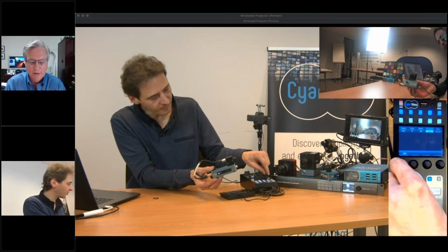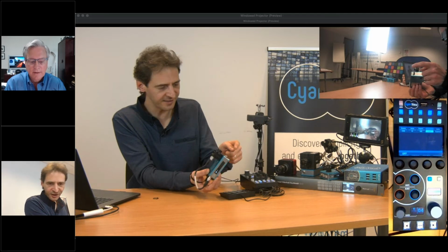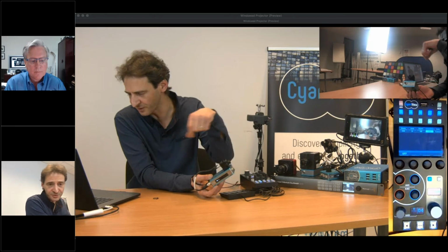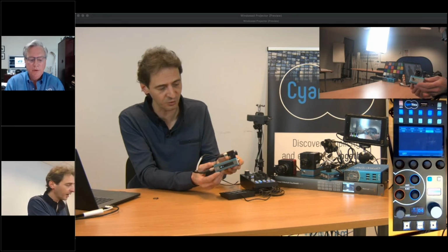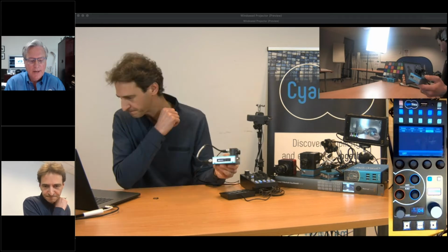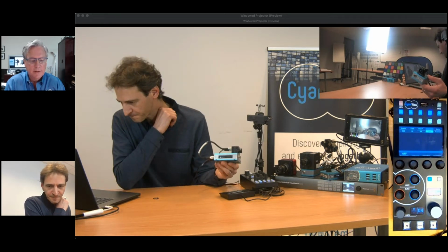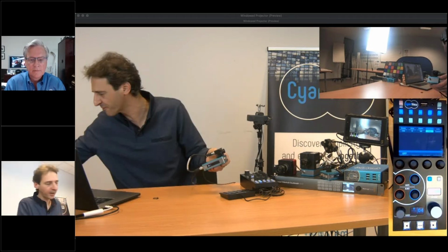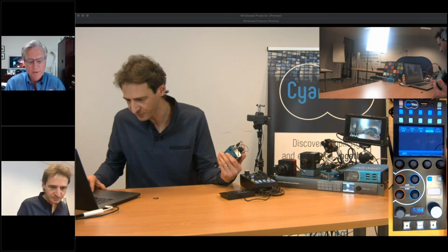You can also add an LED on the side. We usually use the second port, and then you put an LED and you put a lamp or anything that you can control that way. Oh, so you have a GPIO output to control a bigger lamp if you need it, a bigger tally light? We have GPIO, but you can also use the 12-volt output that we have straight there to power the LED directly. So that's kind of easy. I have actually one there. I will show it to you after, but it's a small connector. I put an LED on that, I connect it there, and then you can use it. So now it's on, but I can use it for tally. It's much more visible. Yeah.